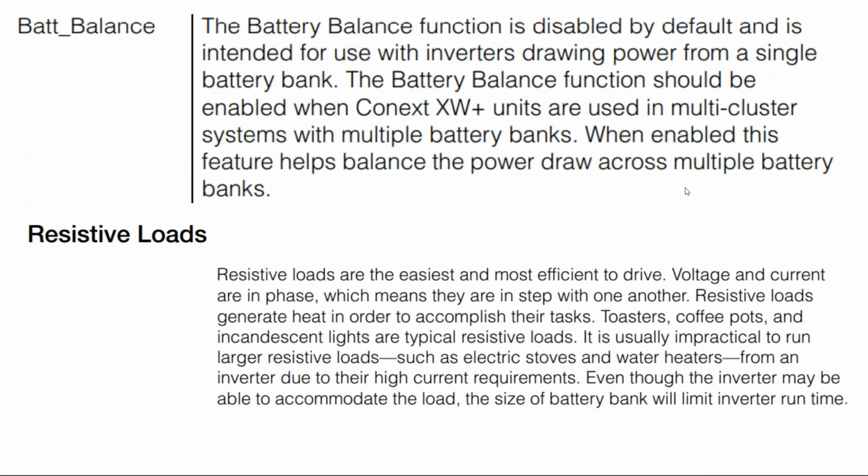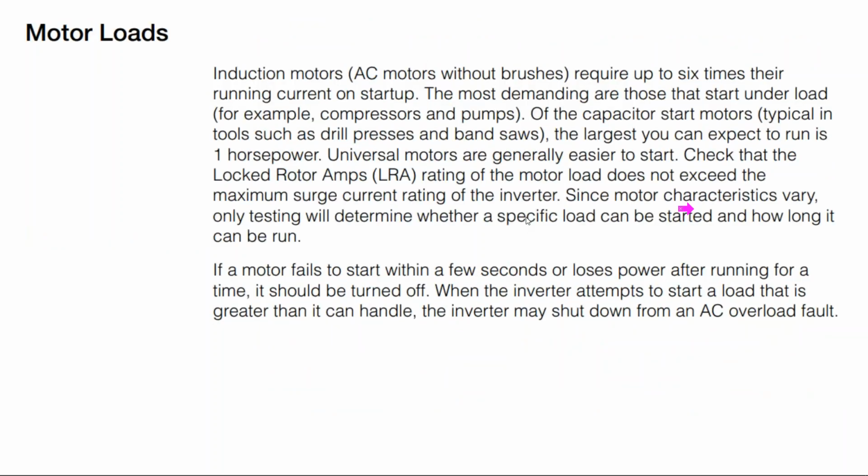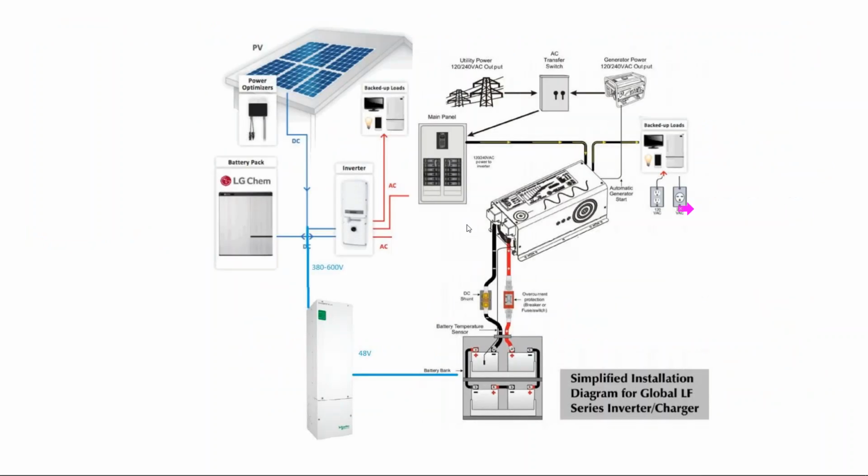We were talking about this yesterday, how resistive loads like heating loads are actually very good for battery banks. It's the compressor loads that are hard. The only issue with resistive loads is they use a lot of energy. So it's not that they're hard on the battery bank. The motor loads are much harder.